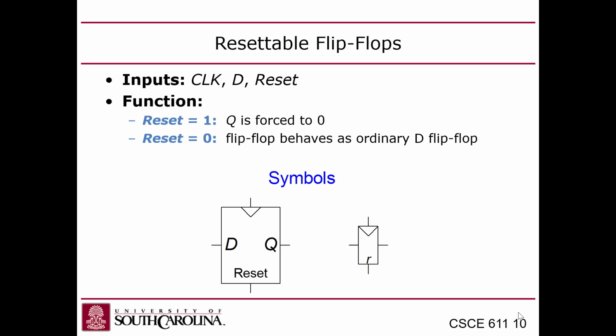So when you have flip-flops and you power them on, they come up in a random state. Even on an FPGA, well, it's a little bit more complicated. With an FPGA, when you program the FPGA, it'll clear all the registers automatically for you. But in an ASIC that's not programmed, that's an actual custom chip, the registers, all the RAMs on there and all the flip-flops will come up random.